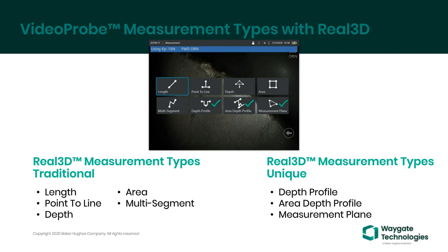What we've done uniquely just recently is also given you the ability to measure with a depth profile where 2 mathematical planes are established on a surface, and you can evaluate the contours or surface profiles and see the height above or below the plane.